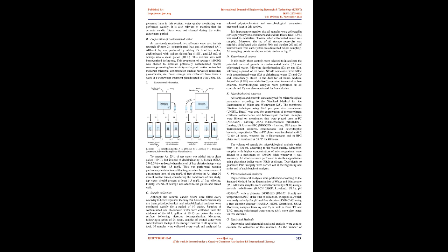Finally, 2.5 ml of sewage was added to the gallon and mixed well. Sample collection. Although the ceramic candle filters were filled every weekday to better represent the way that householders normally use them, physicochemical and microbiological analyses were monitored weekly for a period of 10 weeks. Samples of contaminated and chlorinated water were collected from the midpoint of the 40 L gallon, at 10 to 15 centimeters below the water surface, following vigorous homogenization.